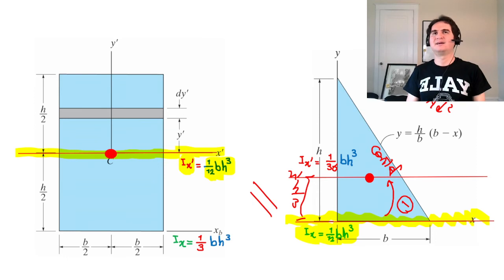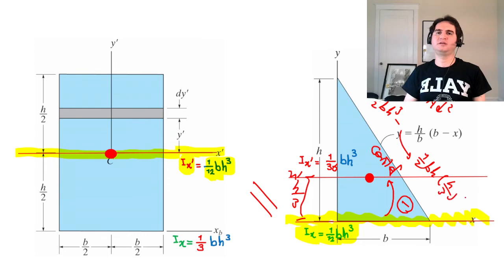That's one twelfth. So definitely the moment of inertia for the centroid would be less than that, because you're subtracting something. That's one twelfth base cube height, minus what? A half of bh times h over 3 squared.